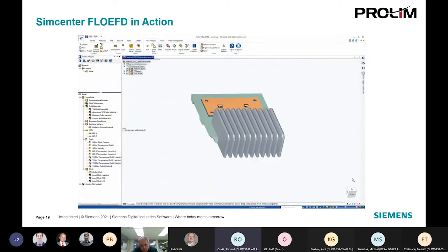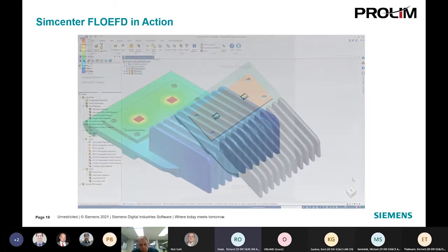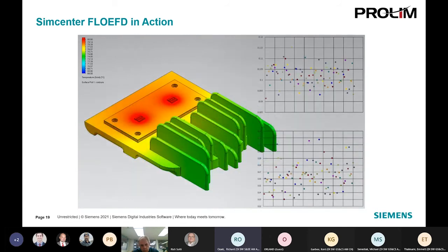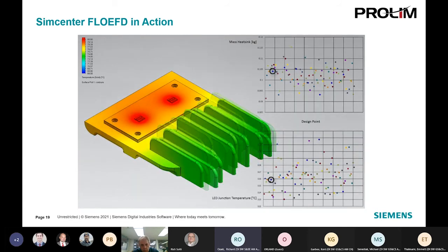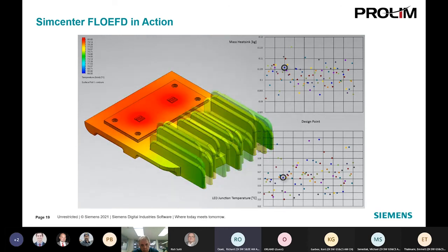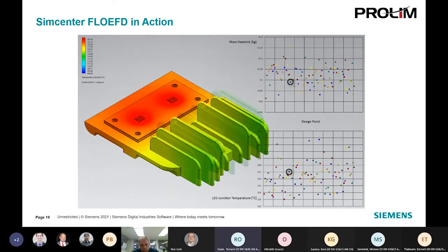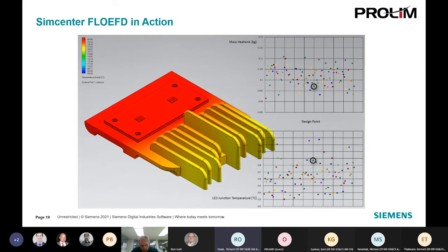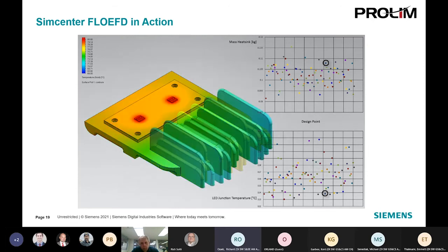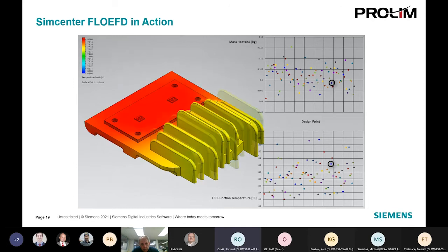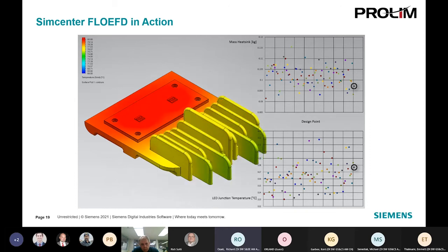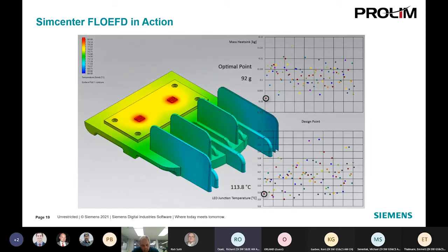This is an LED streetlight, and we've got a heatsink that's been designed here. And again, because we've got access to the parametric CAD features, we can drive variants such as pattern parameters, sketch dimensions. We can use our built-in optimization algorithms to really explore the design space and find the most optimum solution. What's going to get our LED streetlight to operate the coolest, therefore last the longest, reduce warranty claims, and reduce the need to send someone out to actually replace that.